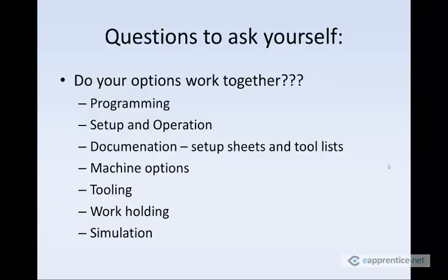That'll make a difference. If you're trying to hold tight tolerance parts, or combine multiple setups into one, you're going to need more advanced tool holding. Hydraulic, heat shrink tool holders, there's all kinds of options. Work holding: are you using dovetail vices, 5-axis vices, things like invertibles? Are you just using a vise that's bolted to your machine table? Are you doing any kind of pallet switching or automation?